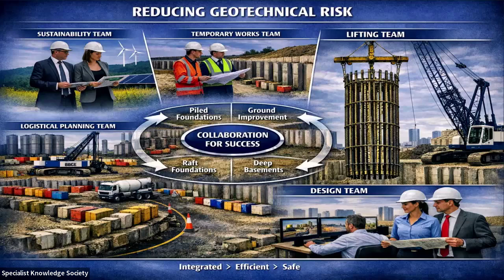For the onshore stuff, rotary bored piles that are constructed under bentonite typically have a reliance on the shaft friction rather than the end bearing for their serviceability limit state. That means the end bearing is important for overall factor of safety, but it's not so important for the settlement criteria. Doesn't mean you shouldn't be concentrating on getting a clean base.